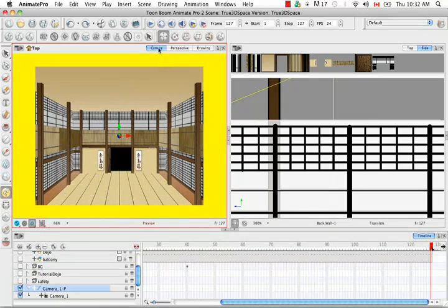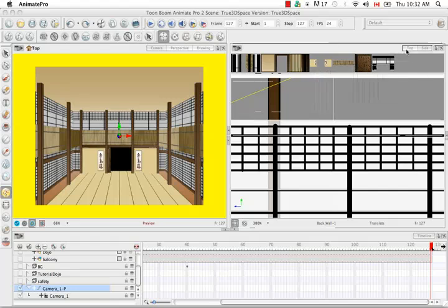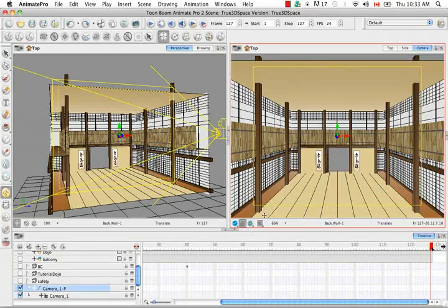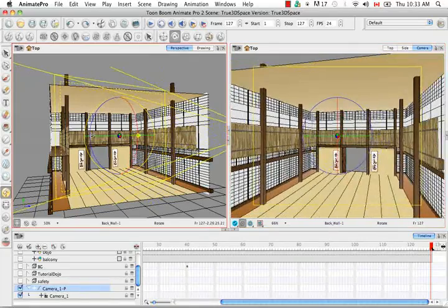And so because we need to use the camera so much, what I'm going to do is actually drag it over and put it here so we can look at what's going on through the camera at the same time as making all our movements in the perspective view. And I'm just going to go back to the OpenGL mode because it's a bit faster to see movements that we've made with the camera. So now that we have everything set up, what I'm going to do is switch to the rotation tool, and I'm going to grab this green circle so I can make a very precise movement and just make a rotation.